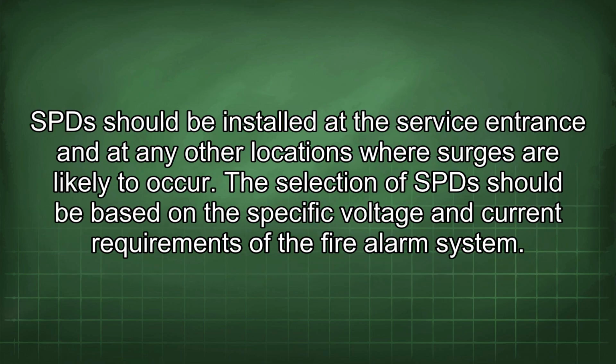SPDs should be installed at the service entrance and at any other locations where surges are likely to occur. The selection of SPDs should be based on the specific voltage and current requirements of the fire alarm system.